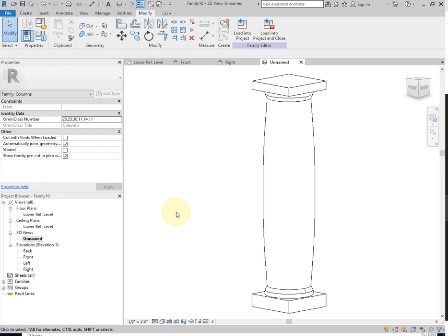So I use the reference lines to aid in making angles and working with the arcs, as drawing them directly within the profile usually does not work. Squared lines works okay, but when it comes to angles and things, you will have problems. So you use the reference planes to create the intersections, you use the lines to make the actual angled parts, and then reference those lines within your profile and making sure to lock those reference lines onto the profile lines that you draw to the reference lines as you select them.